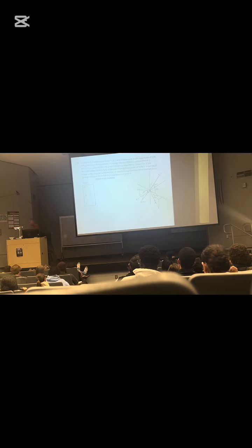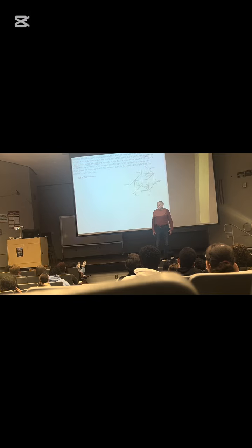Okay. Let's go a little further down the road. Question number 3. Hey, tell me the component of F3 about line DE. Do you know how to do that? Unit vector DE dotted with F3. Done! How hard was that? That's the second use of the dot product. Second. Let's go a little further.